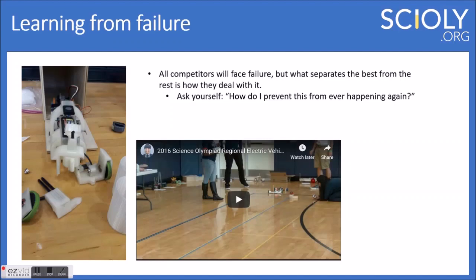We did have a couple things that we improved. We made sure the encoder was having better contact. We made sure to check that very often to make sure that belt wasn't slipping. I believe we also glued a few of those parts in place with epoxy, and we reprinted that front piece to be a bit more sturdy, have more contact. I think we filleted a couple parts, so we smoothed the corners, because having a 90-degree angle corner is not very strong compared to if you just had a fillet where it was smooth. So there's a couple things that we did to improve that.